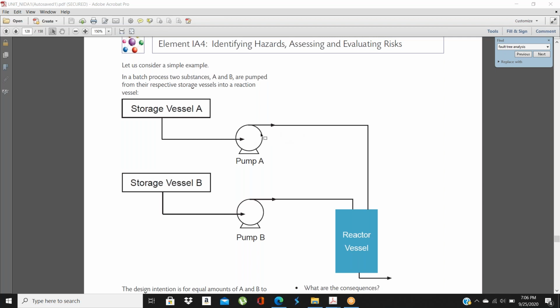Now for the pump, let's suppose the pump is not working. If the pump is not working, the whole system will have zero pressure. And if someone did not switch on the pump, for that we can put one operator, he will check that. Maybe we can make it automatic, we will install some sensor. If the pump impeller is not working, the pump will run but the impeller will not push the liquid. So these are the two pump reasons. We need to make automation for this. We need to install some sensor to make it automatic, so that if we need the pump to switch on, it will switch on automatically.